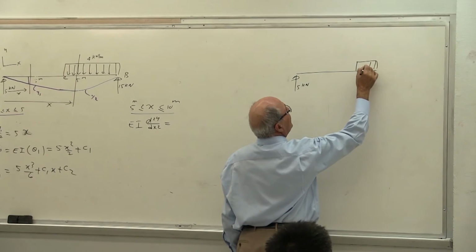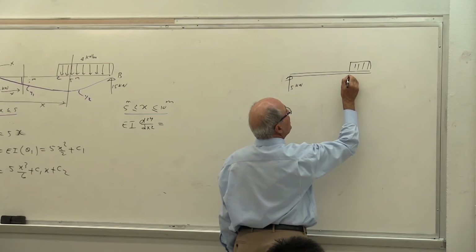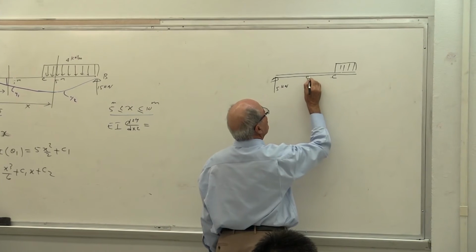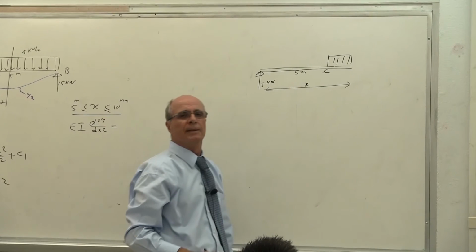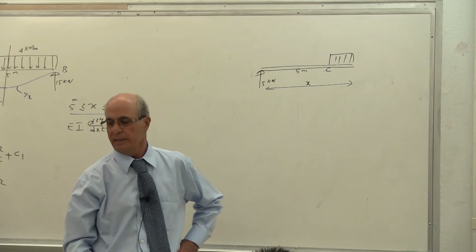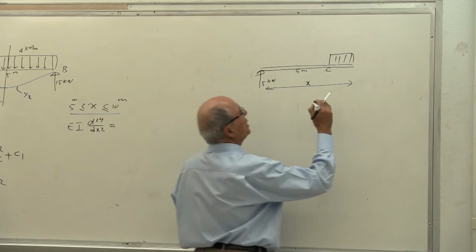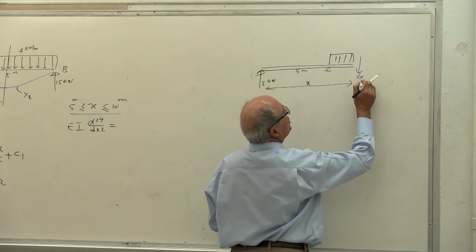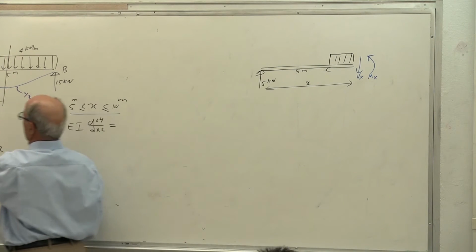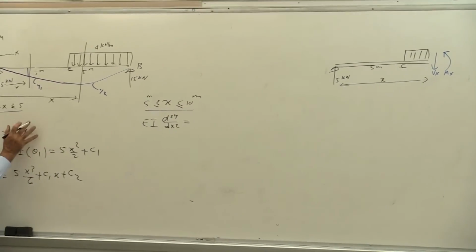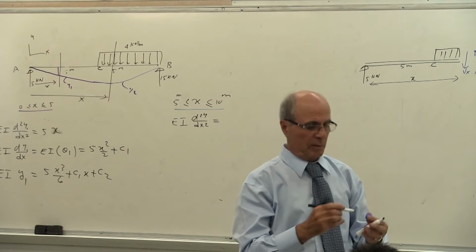You have cut a little bit of the beam, not much, because you are right now where? This is the 5 meter. Is that correct? This is point C, so this is 5 meter. But this distance from here to here is x, correct? Right? And you are calculating, I'm putting here the blue. This is shear as a function of x and m for the blue region. This one actually was the purple one. This is the purple area. This is the blue area. Is that correct or not?